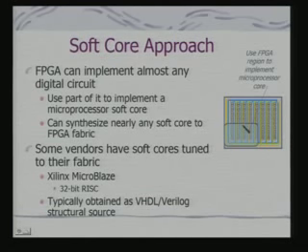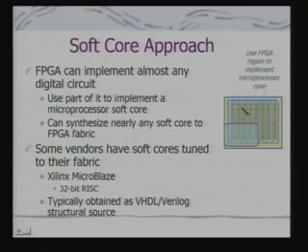Again, if you go back to the camera example, we said that 8051 is available to us in a VHDL form. If we have this kind of a soft core approach, and if we have a parameterized form of 8051 architecture, then we can play with the parameters to get variations of 8051 to meet our requirements.